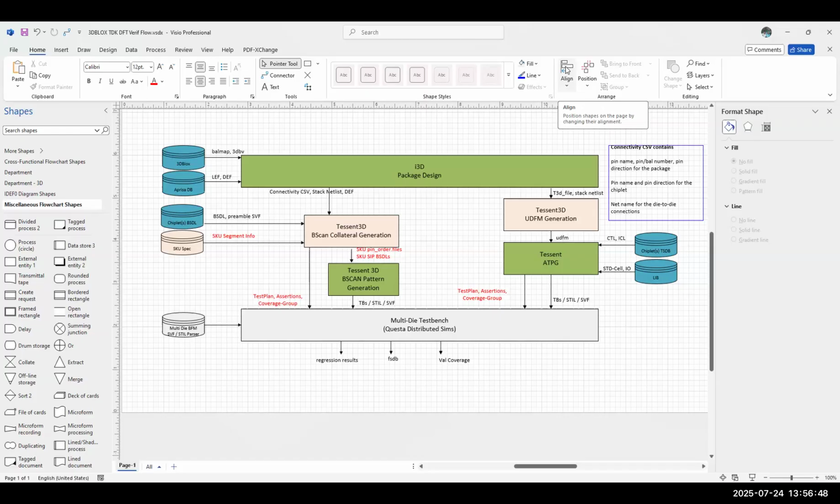So then the boundary scan is really in trouble, where the BSTL generation person at the SIP level doesn't know which fuses affect his boundary scan and in which manner, right? He needs to be told, okay, these fuses correspond to these segments, you need to disable them. Okay, is that fuse identification standard? Is it how they're named? Yes, how they're named, and also which fuse location they are programming. Ideally the platform guys need to have this knowledge of which of the fuses are controlling these IO segments, read those statuses first, and then make sure that the BSTL segments pertaining to those fuses are configured properly, right?